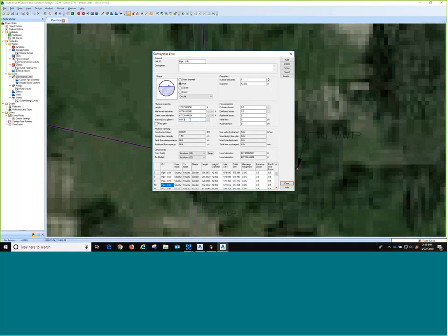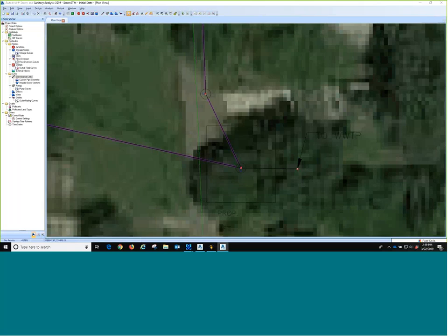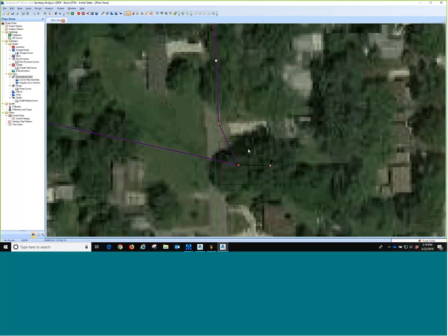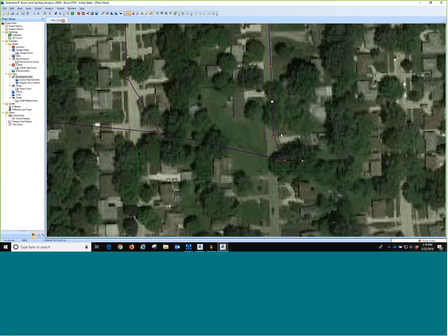There's also in Civil 3D, I could have set up all of these different parts with their own Manning's coefficient, and where applicable, when I go to change it, they're either Hazen-Williams or Darcy-Weisbach coefficients. I could have all that set up for me ahead of time, so then when I import it, it brings all of that information in. So depending on how much setup I do ahead of time and how sophisticated you are, you could really make this a very quick process.